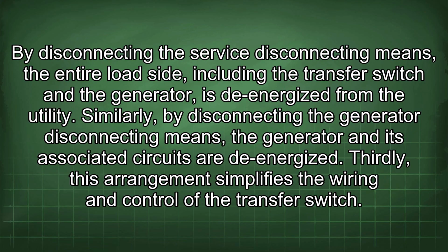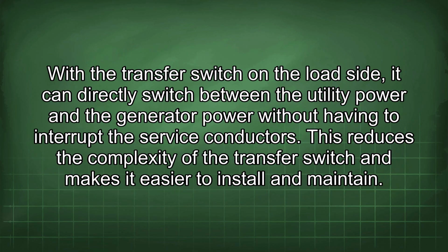Thirdly, this arrangement simplifies the wiring and control of the transfer switch. With the transfer switch on the load side, it can directly switch between the utility power and the generator power without having to interrupt the service conductors. This reduces the complexity of the transfer switch and makes it easier to install and maintain.